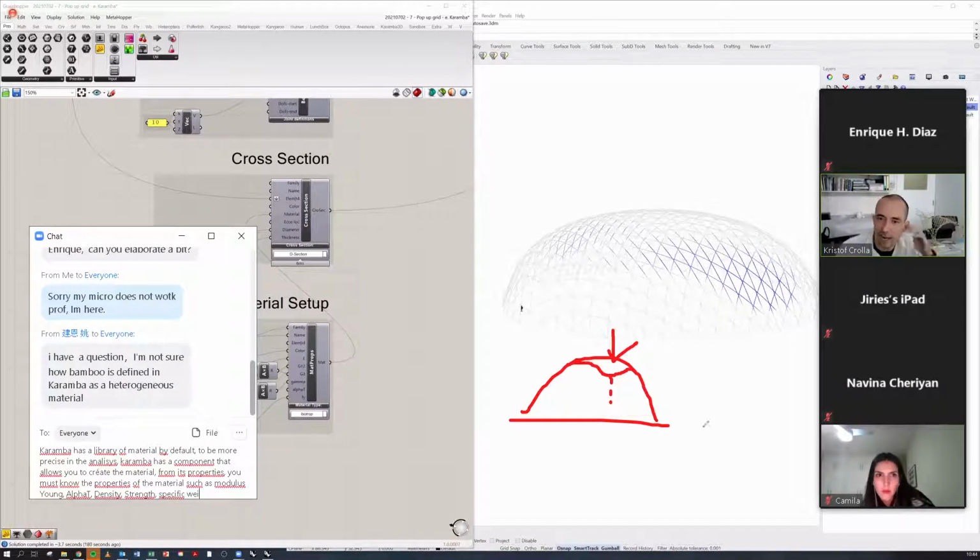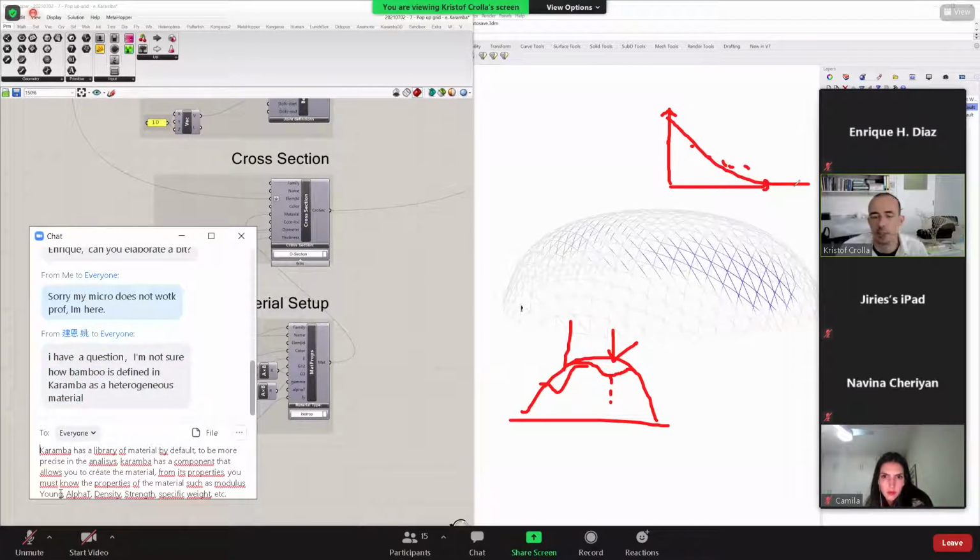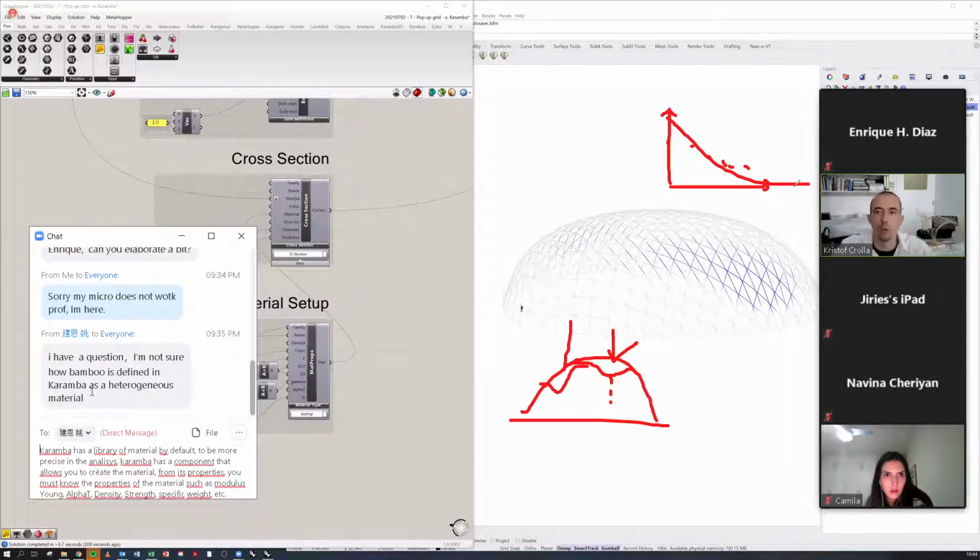Then if you add another load, you'll know exactly where it buckles again. I forgot the details, but you could somehow take your graph and identify at which loads the system would buckle. Eventually they could extrapolate from these study models how the complete shell would buckle under total live load.